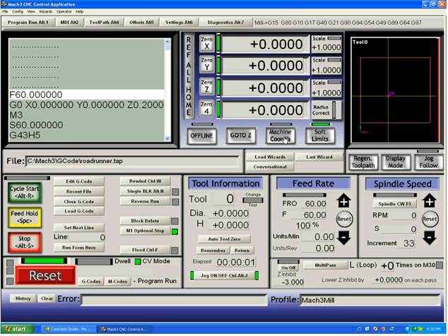By hitting the machine coordinates button, we see some numbers appear. These numbers are the distance from the home switches. So in this case, my Z is 7 millimeters down from its top of stroke and touching the piece. My X and Y is 39 and 41 millimeters from here to here. Normally, you'll only look at machine coordinates if you're trying to figure out where you went wrong.